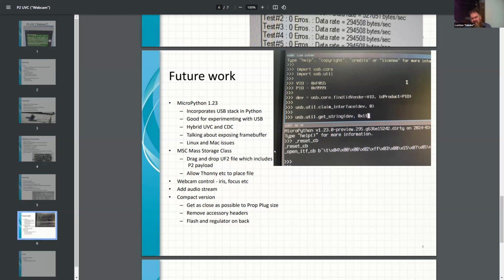What we propose to do is have it so that gets dropped and stored on the Pico's flash, and then the P2 holds the Pico in reset while it retrieves the file from the Pico's flash, and loads. It could be quite a seamless and quite a fast operation. We've done similar things in commercial products before, and we got them up and running, so we don't really see a technical issue with it.